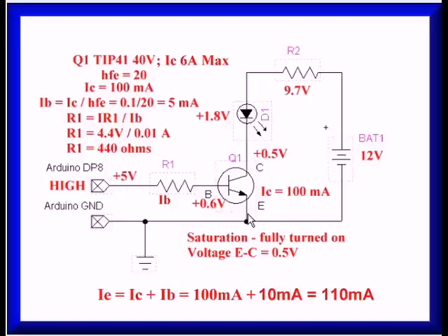Like we had before when we had a push button switch, we want to be able to turn this transistor on so it is conducting from emitter to collector, which turns on our LED. Alright, let's say I need a current level for my LED of 100 milliamps. The emitter collector here is going to have to supply at least 100 milliamps to cut on that LED and make it as bright as I want it.